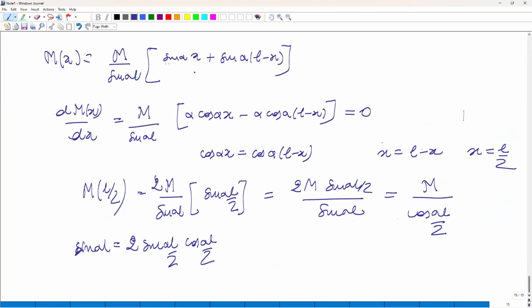And look at it. When the cosinus of alpha L over 2 goes to 0, when alpha L divided by 2 is equal to pi over 2, so when alpha L is equal to pi, the buckling condition has remained the same. No matter if you calculate it on the y or on the moment or on shear force, the buckling condition is always the same because it depends only on the boundary conditions.